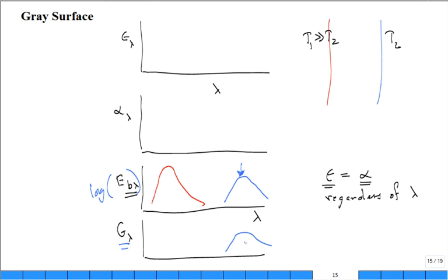All right. Let's take a look and say, what happens if I have the emissivity of this surface very, very low at short wavelengths? Somehow it goes up and is very high at long wavelengths. What's going to happen to that exchange between the two? Instead of having uniform emissivity at all wavelengths, I have low emissivity at short wavelengths. Well, this surface is hot.